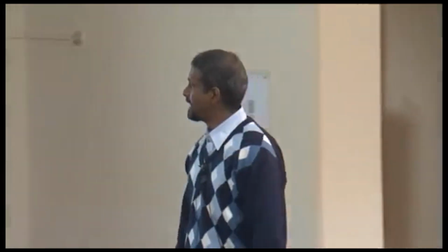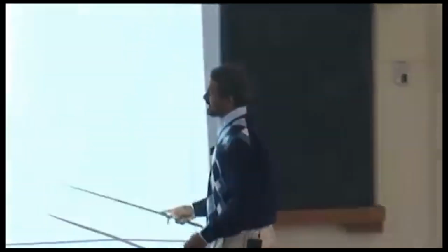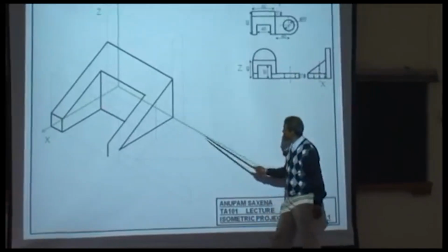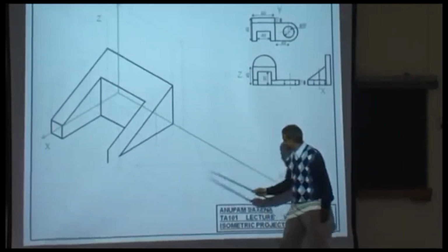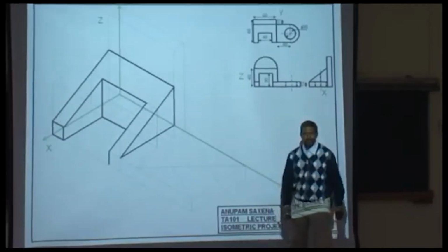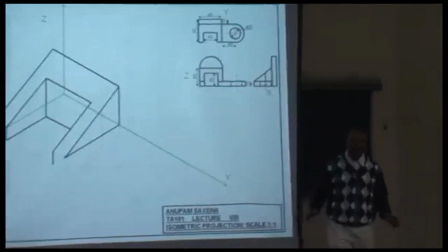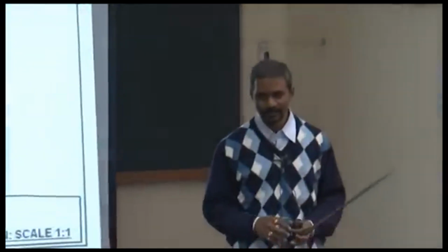And then join this. The rhombus that we use to make the ellipse: to get the ellipse here, this length is 50, this length is 50, this length is 50, this length is 50, this angle is 60, this angle is 60, this angle is 120 degrees, this angle is 120 degrees. You have all the conditions necessary for you to have an ellipse enclosed within a rhombus.